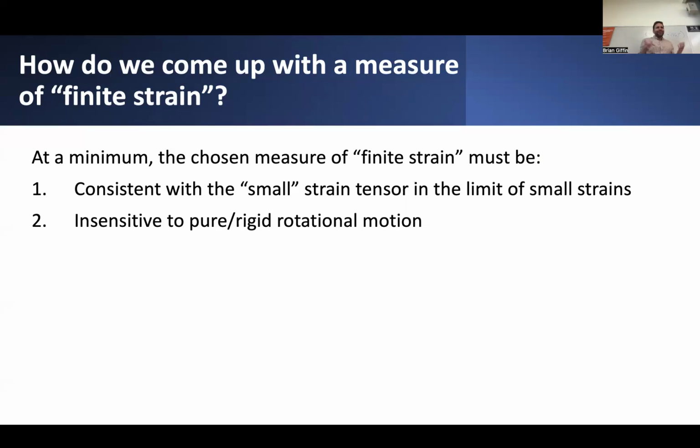So in some sense, what we want to come up with is a description of strain, like this strain gauge that we might attach to this kind of bar that's spinning. We want a description of strain that is attached to the material and rotates along with it. That's a little different from saying, take this bar, let it rotate, and then suppose that we measure the strain by still assuming that the strain gauge always maintained its same original orientation, regardless of how the bar was spinning.